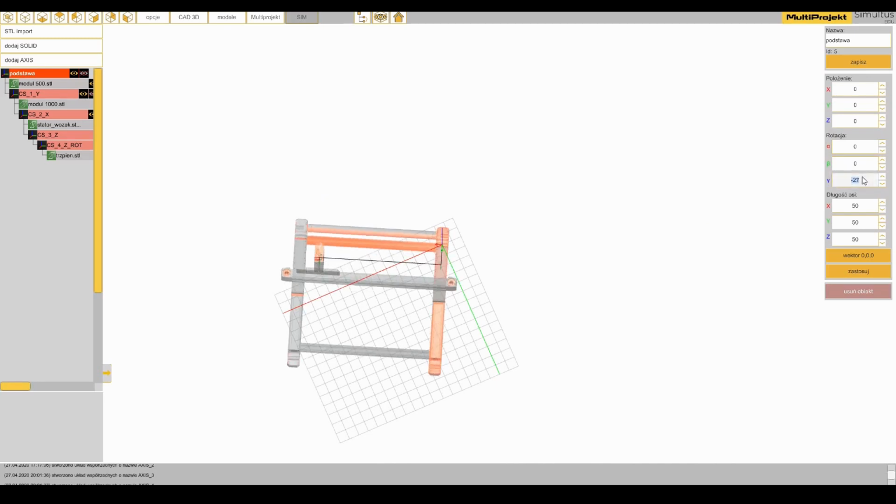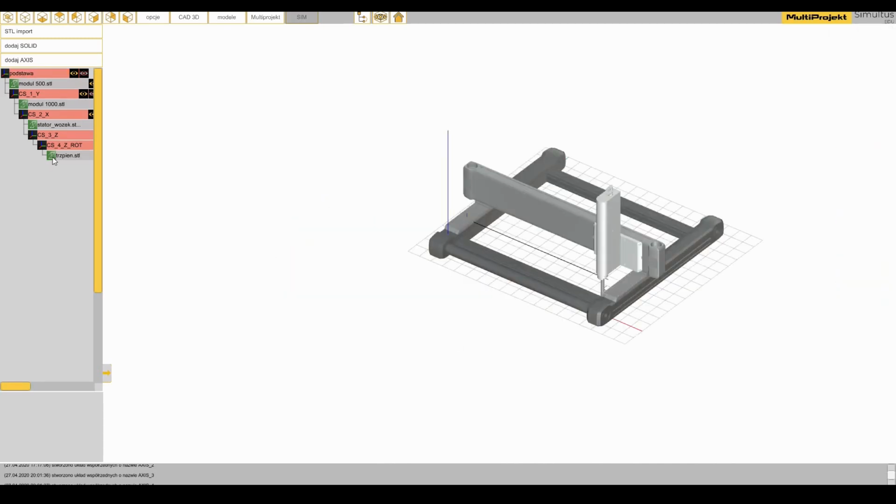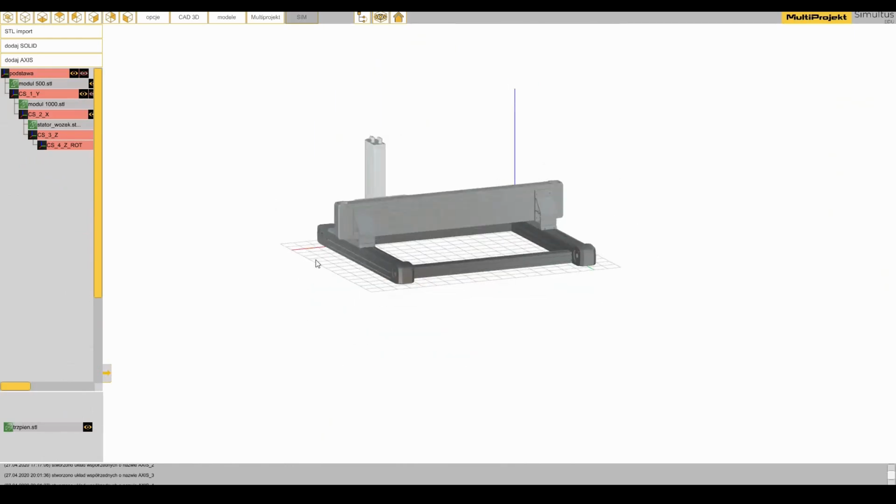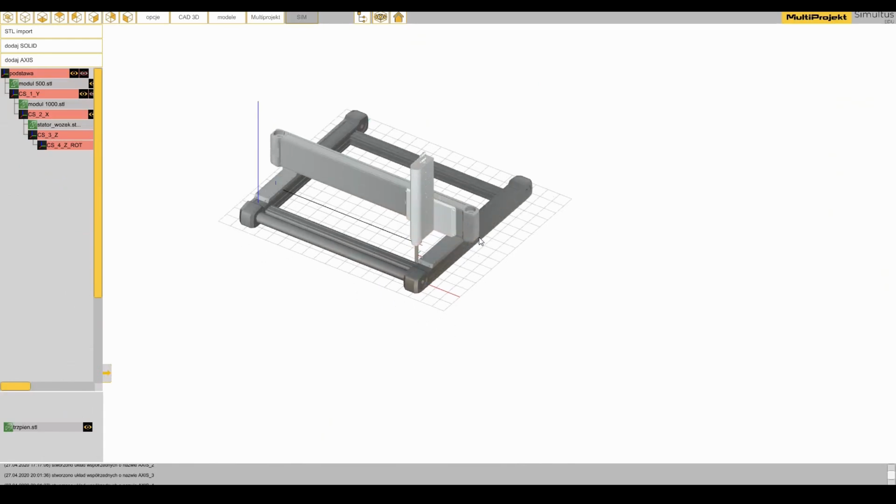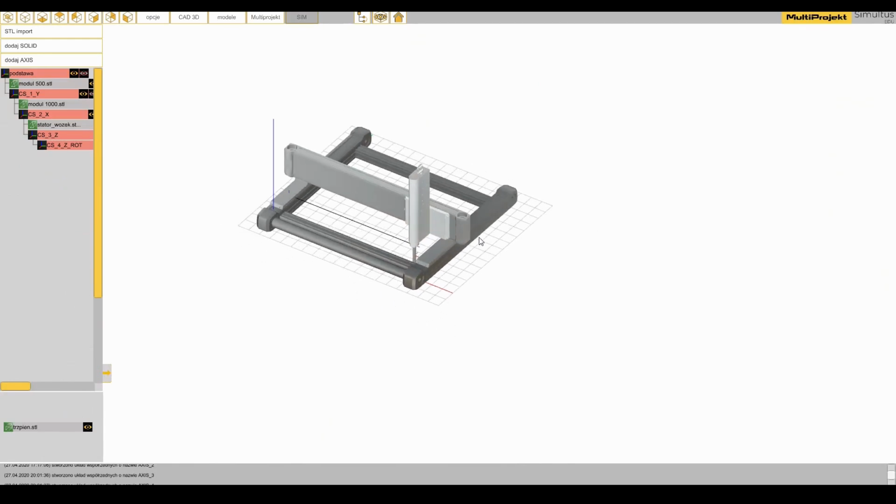We will disconnect it again from the coordinate system. To disconnect the system, we drop it under the tree. Disconnected items are added to the list under the tree. They are not attached to any of the coordinate systems we created, but are currently attached to the main, global coordinate system of our project.